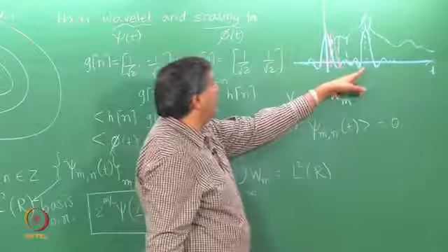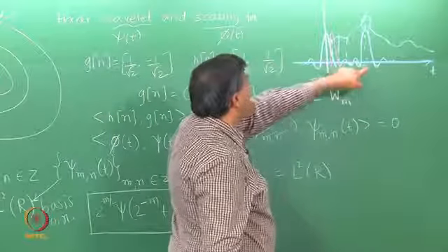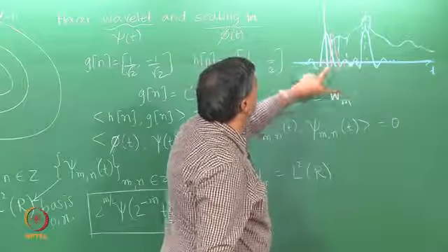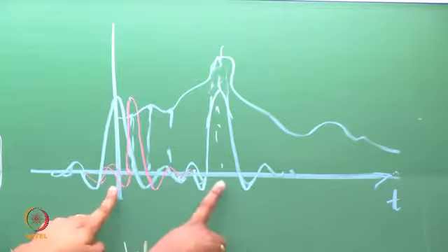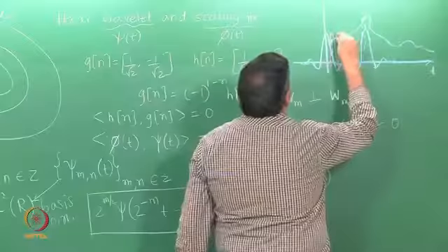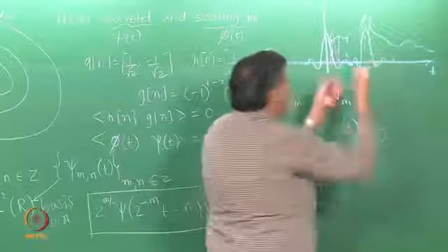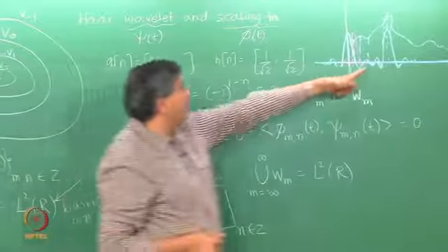Whereas, with the classical orthogonal DWT, there is no overlap between this wavelet, the shifted wavelet and this, but this big shift that I have taken could miss out a feature that would have shifted in time much less than the step you have taken at that scale.